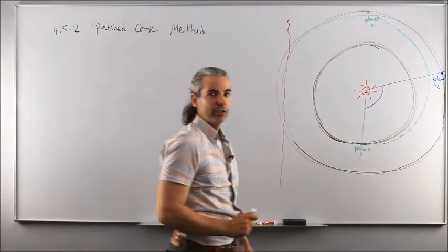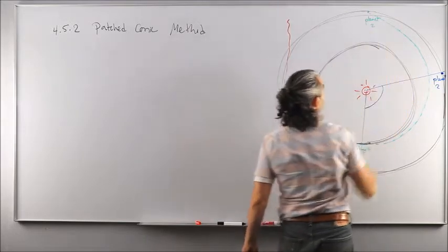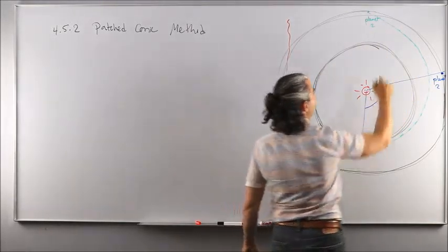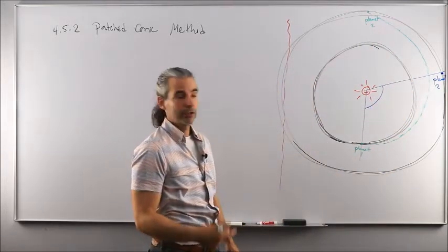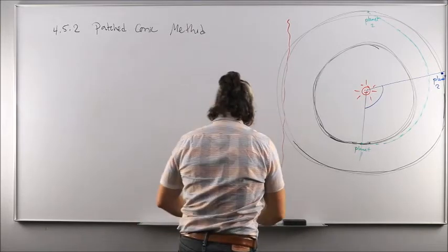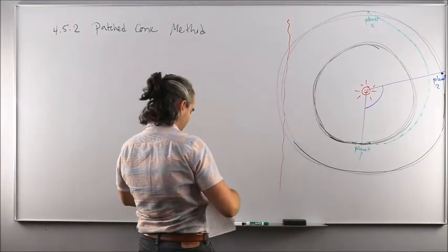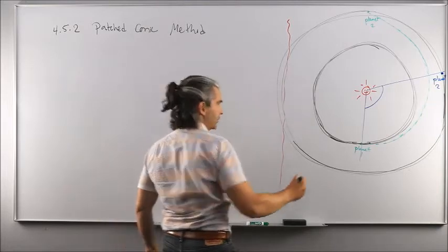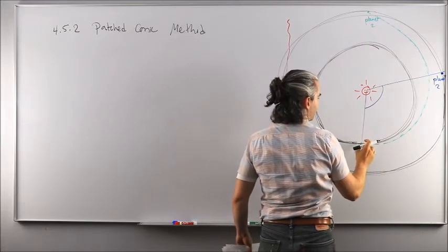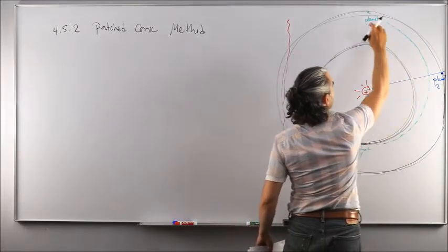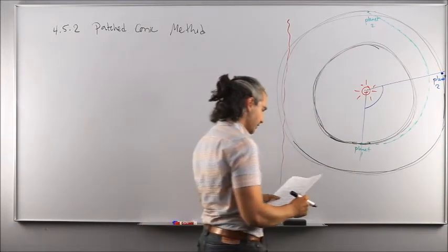at the apogee of its heliocentric transfer orbit, then it's going to meet planet 2 exactly at that point and not miss it. Because if you miss planet 2 here, well, I mean, that's not too good, right? That was the intent, to go from one planet to the other one. So we need to time things properly to ensure that planet 2 advances its orbital position in terms of angle by a given amount based on the heliocentric transfer orbit dimension. Okay? So we're going to look at that first.